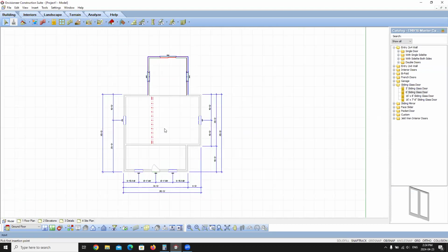But now we want to add a roof. When you add a roof onto the structure, it will either quantify all of the elements, or it's not going to quantify it at all. So we will step through how to quantify only the portion of the roof for the new addition.